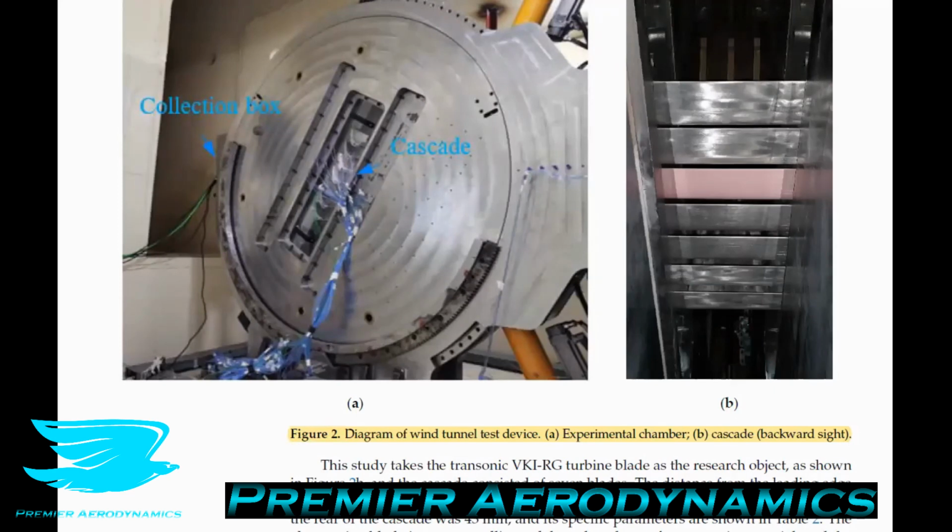The camera and excitation light source were integrated into a specifically designed collection box and installed above the back of the test section. This study takes the transonic VKI-RG turbine blade as the research object, as shown in figure 2b, and the cascade consists of 7 blades. I should note that only 1 blade was painted with this TSP, the third blade from the top.